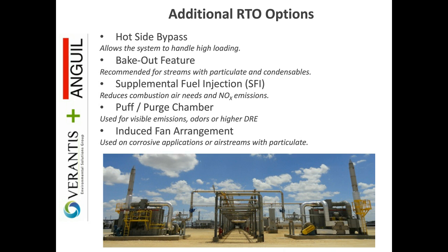Bake-out feature. The best way to think of a bake-out feature is like a giant self-cleaning oven. If you get some buildup of organic particulates within the ceramic itself, we have this built-in feature where we'll offline get the temperature within the beds to 600 degrees Fahrenheit or hotter in some instances. It'll volatilize any of the organics built up, turn them to ash, and essentially just blow out the stack. Again, similar to how a self-cleaning oven works.